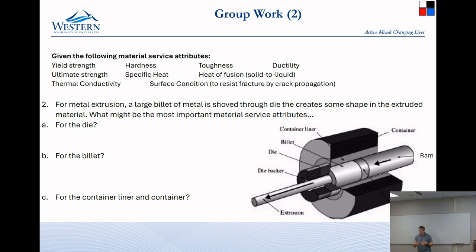It pushes in there really hard, and the die has this big shock that it has to endure. If you have a really good control system and a good way to control the friction, the other thing that can happen is stick-slip friction, where you push it and it sticks and it sticks and then it slips, and that can also cause a lot of pounding on the die.